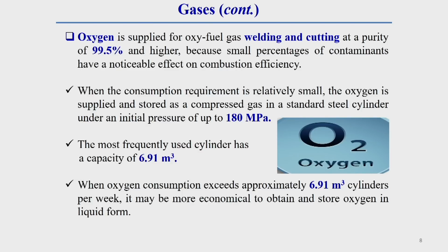First of all we will discuss oxygen gas. The oxygen gas generally used for oxy-fuel welding techniques should have a purity of 99.5% and higher, because you should keep in mind that a small percentage of contaminants has a noticeable effect on combustion efficiency.